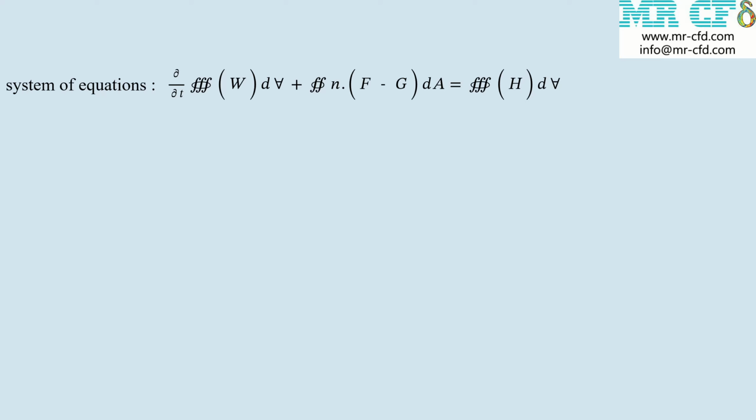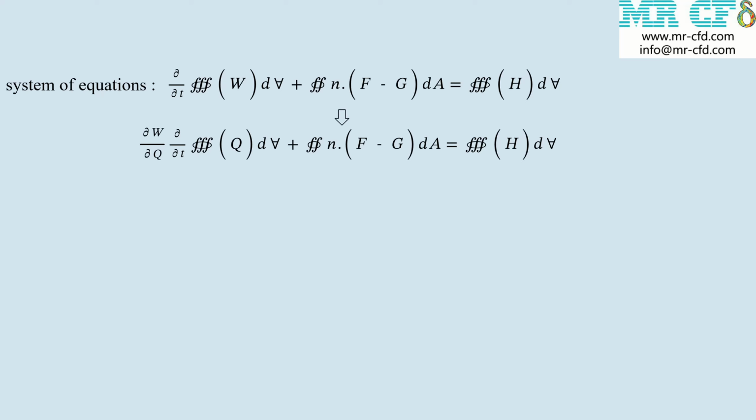The Navier-Stokes equations, as expressed here, become very stiff at low Mach number due to the disparity between the fluid velocity and the sound speed. This is also true for incompressible flows, regardless of the fluid velocity, because sound travels infinitely fast in an incompressible fluid. The numerical stiffness of the equations under these conditions results in poor convergence rates. This difficulty is overcome in ANSYS Fluent's density-based solver by employing a technique called time derivative preconditioning. This has the effect of rescaling the sound speed of the system of equations being solved in order to alleviate the numerical stiffness encountered in low Mach numbers and incompressible flow.